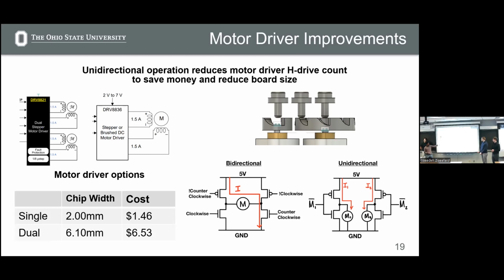But if you look above in the CAD rendering of the cam and follower design that we want to use, you'll notice that the profiles aren't really bidirectional. They very slowly go in one direction and then quickly drop off in another direction. So if we attempted to move the cam in both directions, the pins would prevent movement. And this makes the direction of our cam and follower unidirectional. And so if we have a unidirectional cam and follower, then why would we need a bidirectional motor?